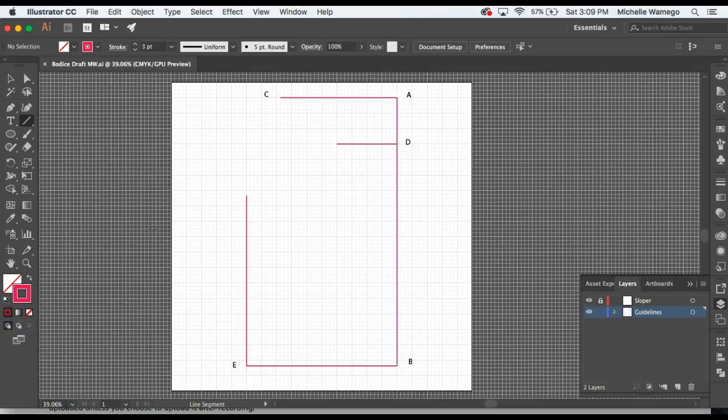Now I'm moving down to the bottom half of page 40. These are going to be the markings for figure 2. B to G. Oh, we missed a squared down line here from C, so I need to move my cursor so it snaps to that point at C. I am going to use my shift key, so I pull that straight down. Again, it does not say exactly how long, but approximately 3 inches should work so that I have a guideline to run into. Now, moving on to figure 2, B to G.